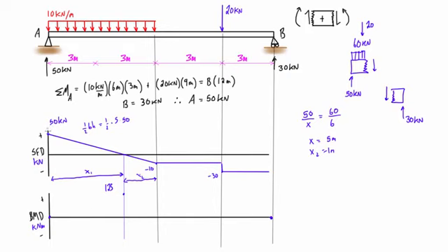So where we also have, if you remember from the Mechanics of Materials playlist that we did, a shear force diagram, or maybe that video actually showed up in statics, I can't remember. Anyways, in sections of the shear force diagram where the line is not horizontal, where it's sloped, we're going to get a parabolic shape in our bending moment diagram. So it's going to look something like that. And where the shear crosses 0, you're typically getting a local maximum or minimum on the bending moment diagram.